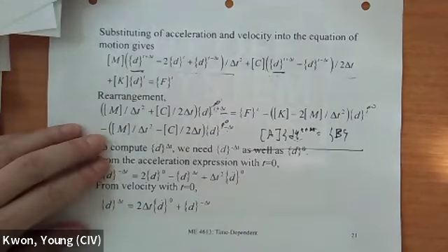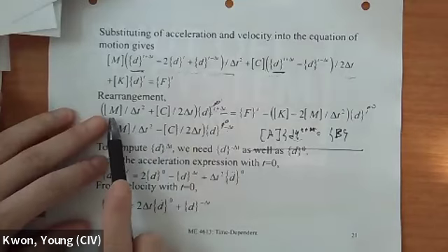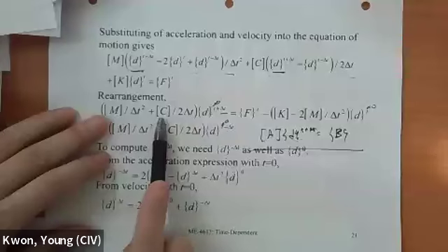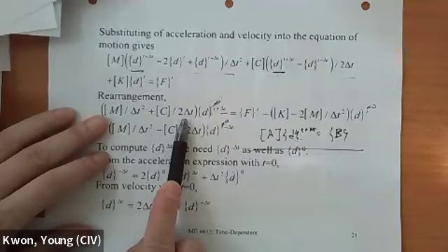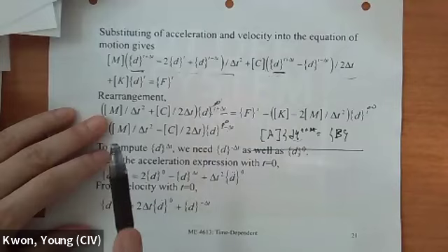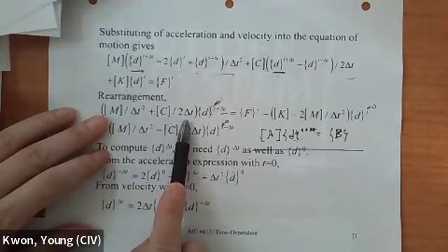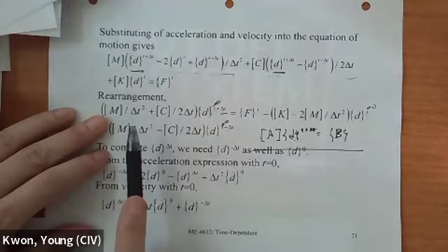And secondly, if you look at this term, I have a mass term, damping term, okay, but I don't have stiffness term, right? I don't have stiffness term. So if you don't have stiffness term, means this is going to be unconditionally stable. So in other words, delta t have to be small to control the stability. Okay, that's what you can see there.